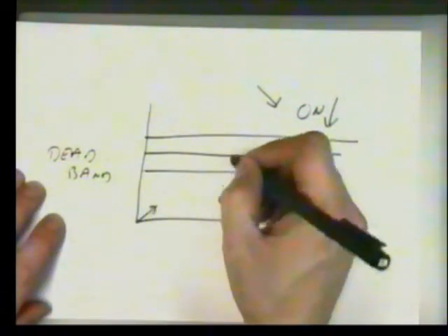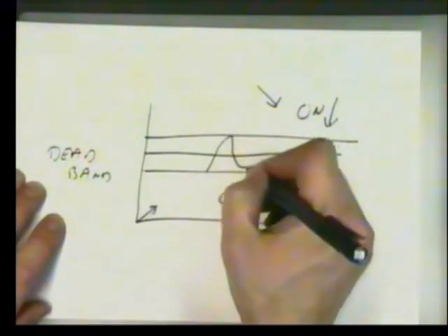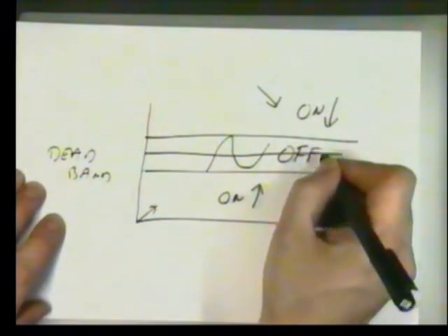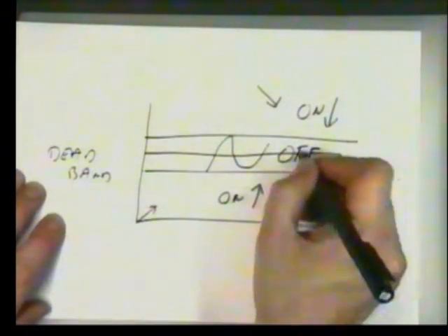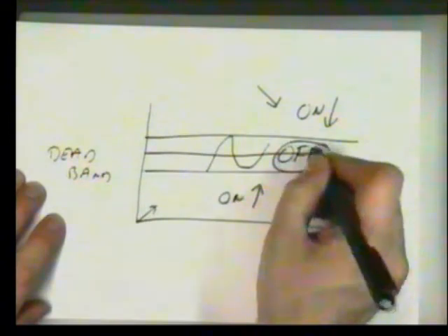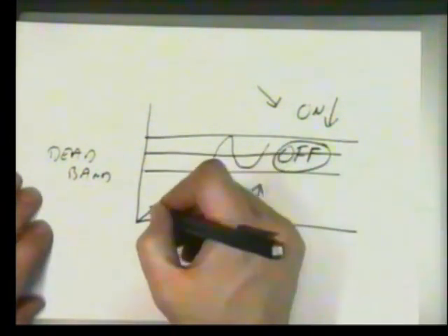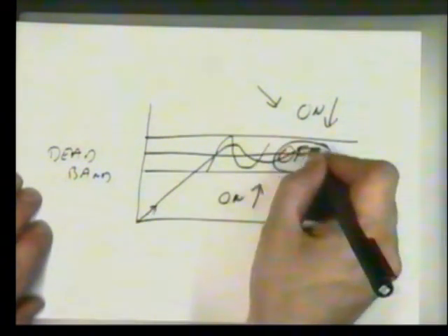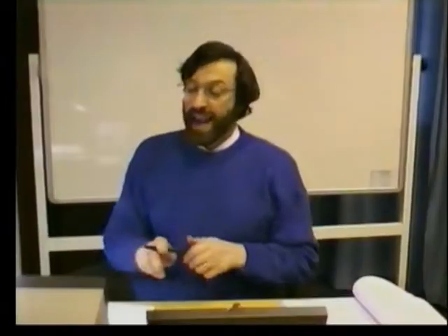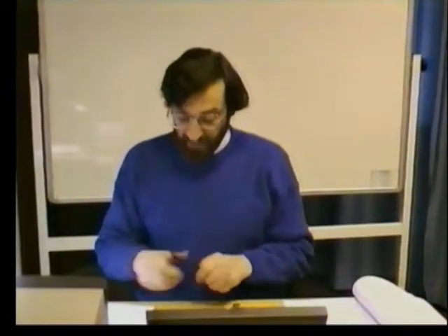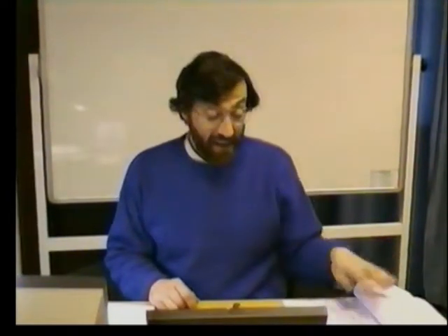If you're above it, you drive down. But if you're in between the two, then you must have both motors, both systems, heaters and coolers, whatever they are, they must both be off. And the idea is that you will then trap the measured variable inside the dead band. Very simple. But there are, of course, more precise mechanisms.